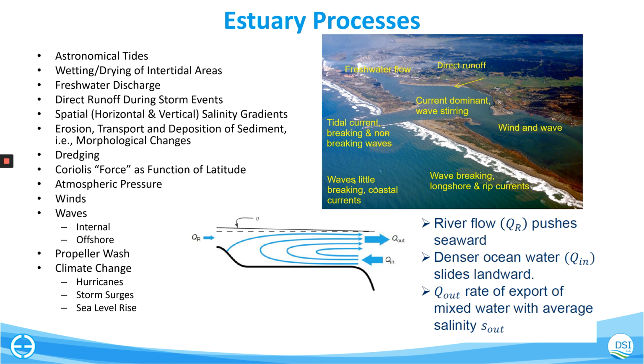So wind and waves, we've discussed those. Propeller wash, that's a big topic that we are concerned about here, especially in a lot of harbor areas where large container vessels might be sitting at berth with their propellers running, or might be warming up to push off and be kicking up sediment all that time. Depending on what's in the sediment, that might be a problem.